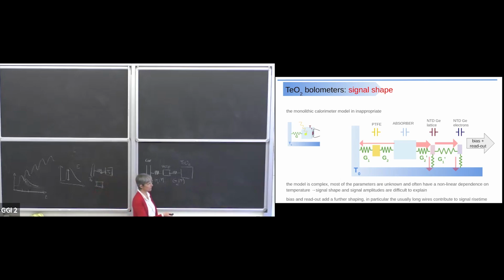In the thermistor, we have, first of all, of course, the glue, and let's neglect the heat capacity of the glue. And then we have the thermistor, and the thermistor has wires. The wires are connected in some way also to the thermal bath, because they are metallic wires, and so at the end they provide an additional conductance to the thermal bath.